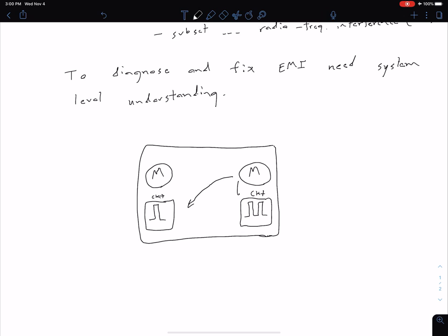There were pulses coming from here, and there were pulses coming from here. These pulses of electromagnetic radiation were being interpreted as pulses in both of these pulse counting circuits. So the software sees all these random pulses and then tries to correct for that to make both motors move at the same speed, and both motors just end up moving spastically.